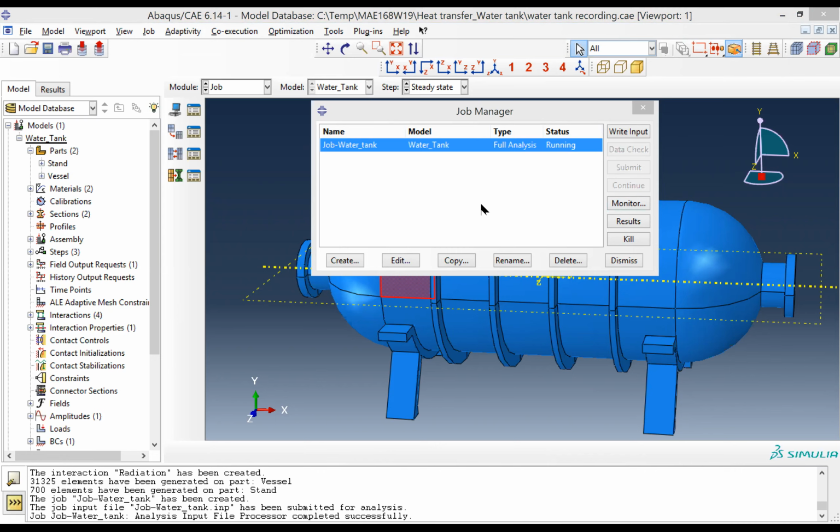All right. Another important tab to see is the data file. This is also a file created, and you can see different steps and all the progress in the submission. And finally, we have the message file. Every time we have some fatal error, we need to come here and take a look at exactly what happened.